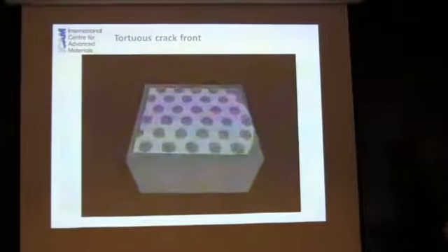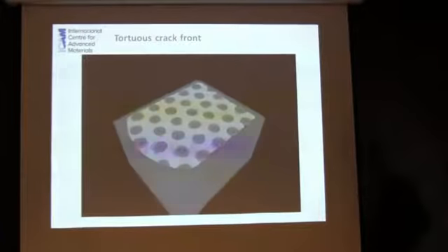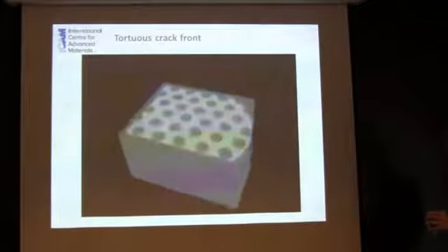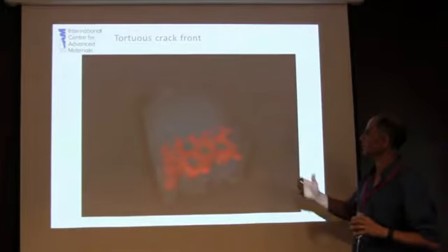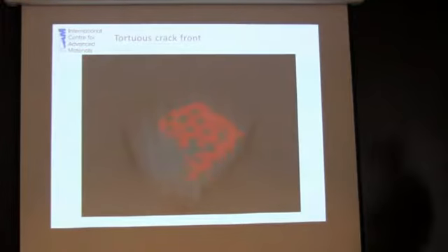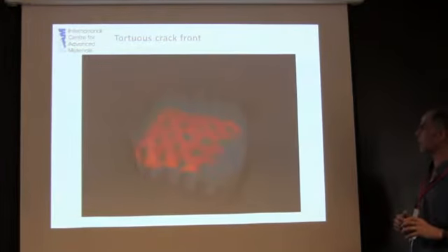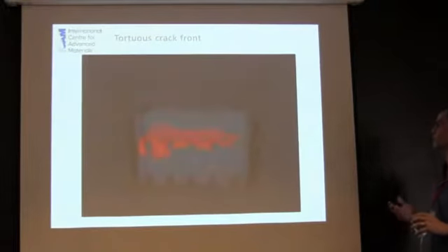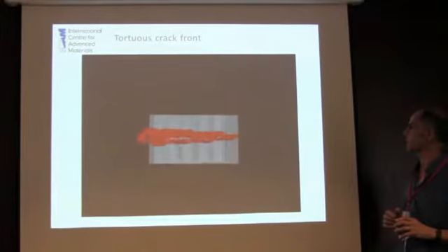Right, okay. So I was going to just show some of that, just a little bit of an insight into that. This is a titanium silicon carbide composite, and we can image that in 3D, and of course, because it's three-dimensional and non-destructive, we can image the crack growing. And here you can see the crack growing, and in a complex material like this, the crack doesn't grow straight, the crack doesn't grow flat, and in fact it bifurcates as it goes past each fibre.